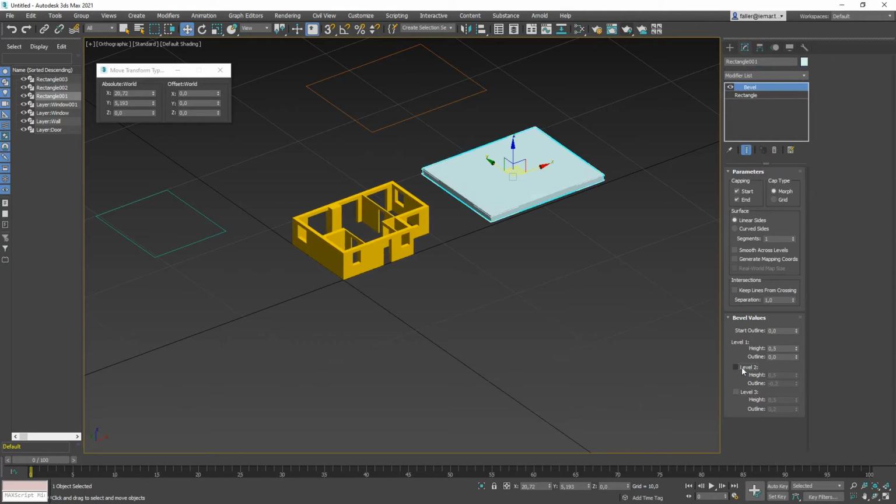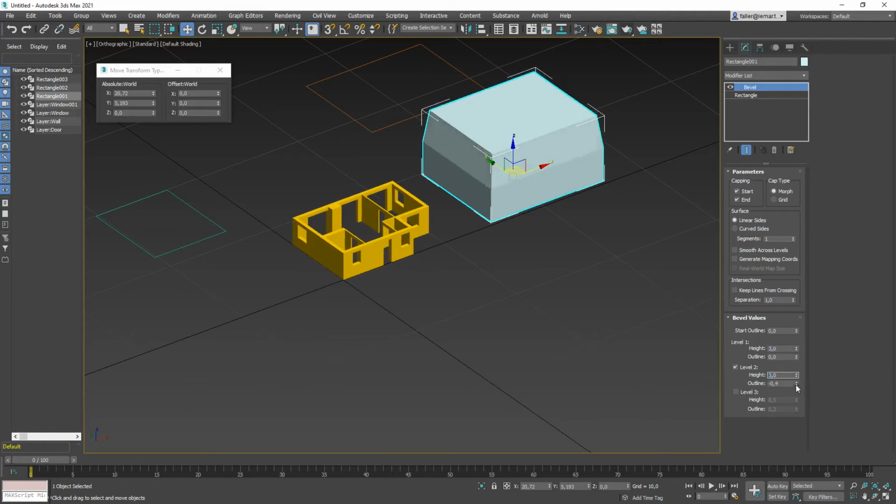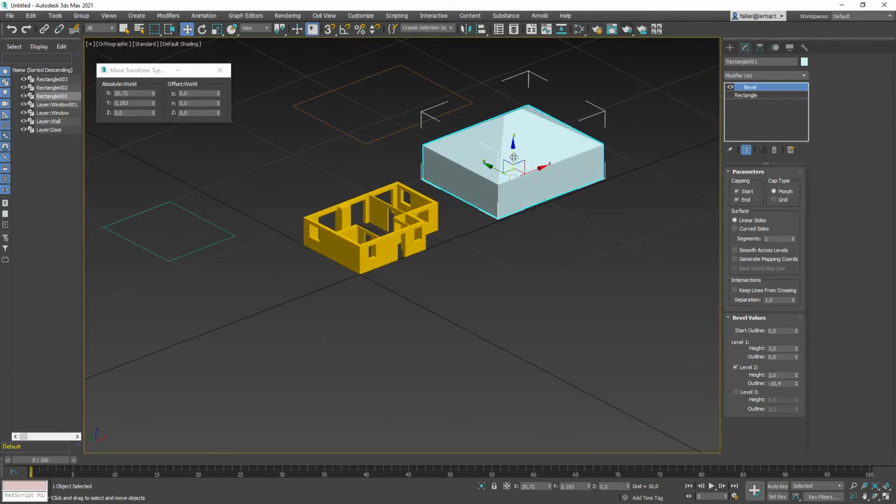This is just the same thing as before. And now you define the first height, which is the height of the ground floor. Let's make it 4 meters. Okay, this is 2.5. Let's make it 3 meters. So it's about the same size. And the first level and the second level then will be another 3 meters. And I'm going to use the outline to minus and pull it all the way down there. And here, what it does, it creates a roof for you. So you can create a single low resolution, low level of detail house